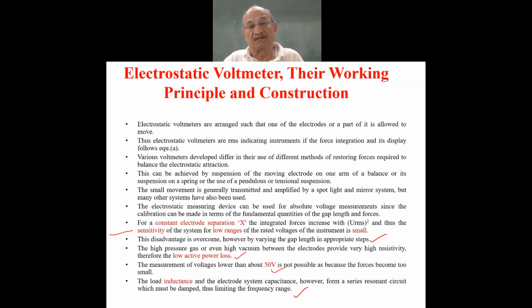I have come across electrostatic voltmeters working simply in air, but the size of the electrostatic voltmeter is large, and you have to change the range, and the sensitivity is there of the reflection of the mirror on the calibrated scale, etc. So all these things, once again, have not promoted the use of electrostatic voltmeters very widely, although it's a very nice and accurate measurement of power frequency voltage, and RMS value of power frequency voltage, and also of high frequency voltage, and also DC voltages.